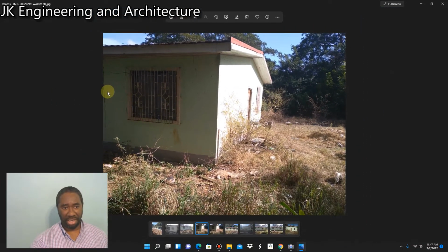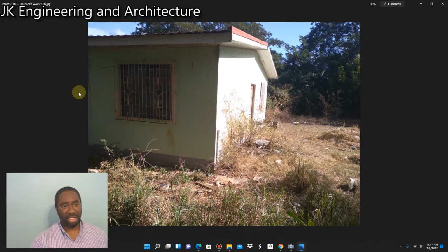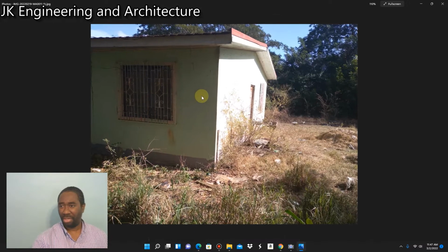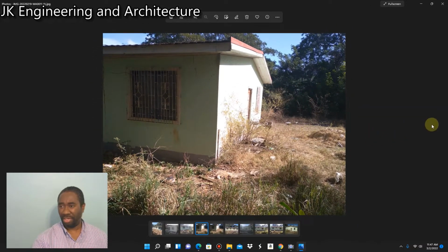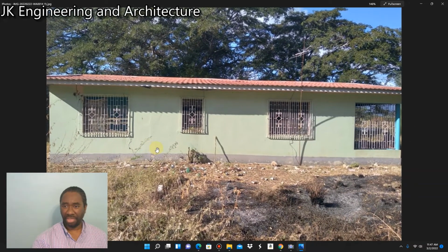As you can see, this is one of the shear cracks here, or cracks due to flexure. These cracks mainly develop because of soil movements, probably due to settlement in the foundation over time. And where there's no stiffener, you know there's going to be a weakness. This is what the building looks like from the side.